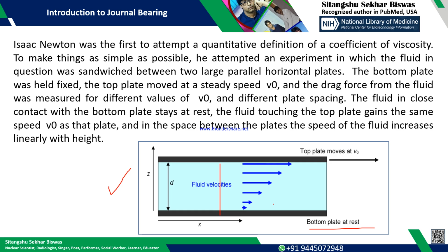This gradual degradation of the velocity is more prominent if you replace the liquid with a more viscous liquid. In this way, Sir Isaac Newton first tried to conceptualize and quantify the parameter viscosity. And as I told you, that parameter is very important to design the journal bearing.